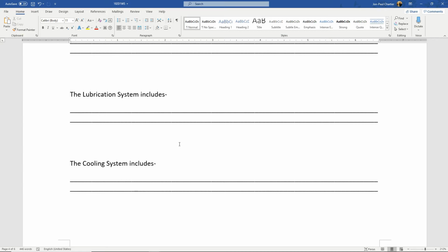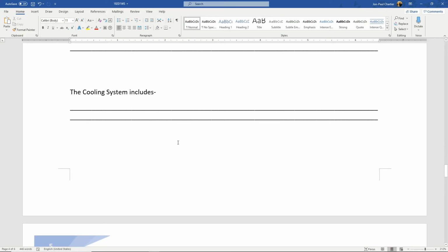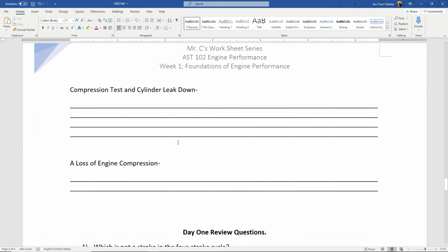Cooling system. We went over this when I was telling you guys about when to open the radiator cap. So hopefully this is not new, but it's very simple. We know we need coolant, right? We've got to have something to exchange thermal energy. To move it around, we'll have a water pump. To keep it in the engine or in the radiator and then allow it to move, we'll have a thermostat. We're going to have hoses, the actual heat exchanger itself, the radiator, and a fan on the radiator, plus the cap if the pressure gets too high to allow the coolant to leave.